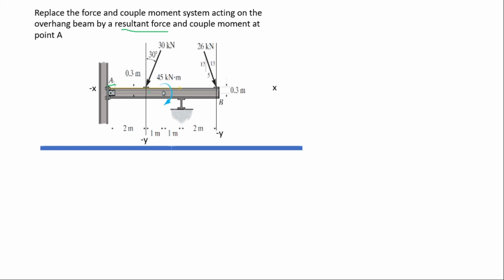So we have the x component. Now this force is coming down. We are using the principle of transmissibility, so this arrow can come here. And here is 30 degrees. With vertically opposite angles, automatically here becomes 30 degrees. But note, we only work with the angle which is made with the positive or the negative x-axis. So if here is 30 degrees, automatically here becomes 60 degrees. So we are working with this angle.